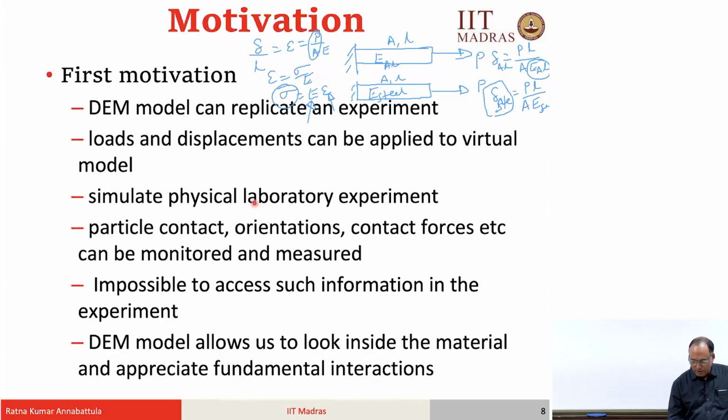So, for example, if you plot the stress strain response of any material, it looks something like that, right. For example, it is a linear elastic material and then it becomes non-linearly elastic. Let us say you are only interested in the linear elastic regime. Then the relation between say stress and strain is given by a single slope because it is linear. But what